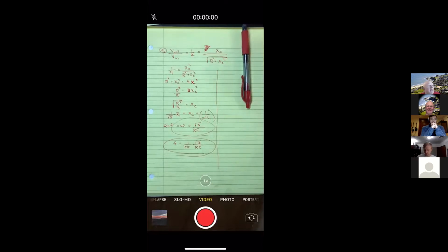Yeah. So let me just take Faraday's law, which says the EMF, so that's the voltage, is equal to change in flux. So there wasn't really a good set of calculus that had an integral with a B dot dA. There was none of that kind of symbol. You just wrote it in words that it was the change in flux. And so you kind of looked at the flux and you said, well, this magnet has 4 Webers, and then you pull it away. So the change is 4. And you took it away in about a half a second. So, all right, 4 Webers divided by half a second, that's 8 Webers per second. All right, so the EMF on average is, so it's not to say they weren't doing some math, but it wasn't calculus. It wasn't vector calculus. It was more of an algebra.